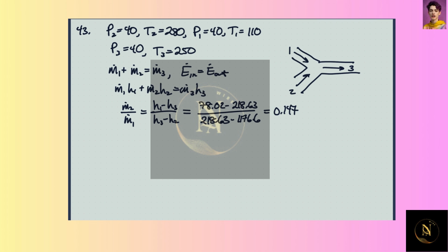So basically about 15% of this would essentially be what goes into the turbine in the end, out here. And this would be what we bleed off of the turbine. So again, it actually might be a better analysis to look at m dot 2 over m dot 3. But in this case, basically, we know that we have to have the ratio of the cold water coming in. We need about 15% hot steam coming in, and then the colder water.